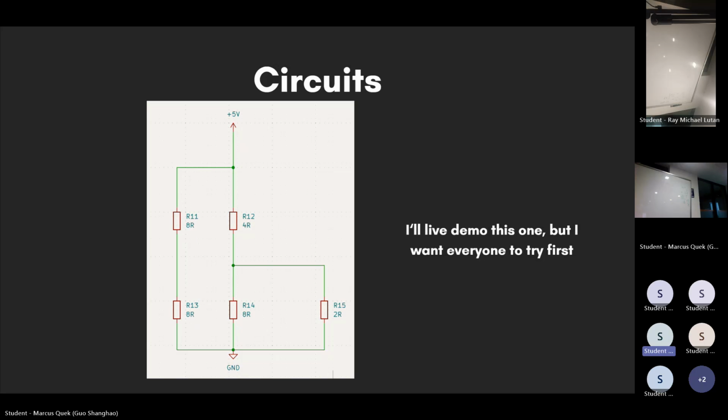The result should be lesser than each individual resistance. With 8 and 5, you get about 3. It should decrease. If you get something higher, you calculated something wrong. It's easy to check.